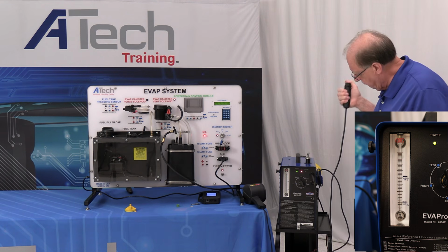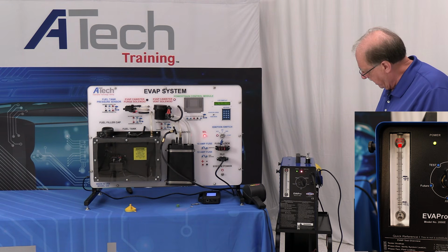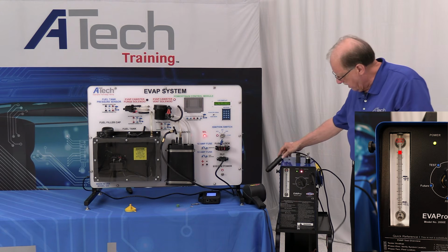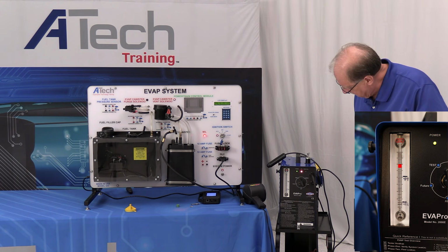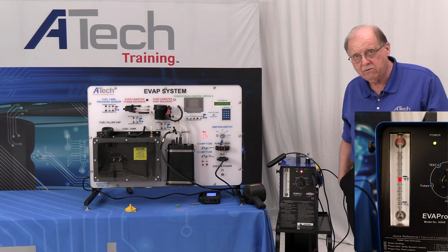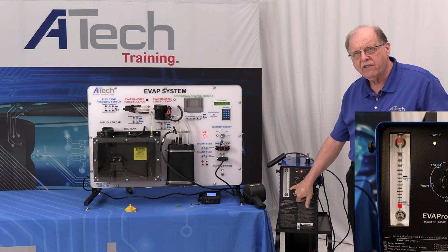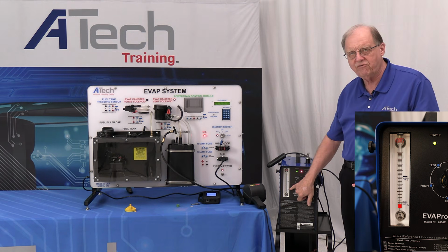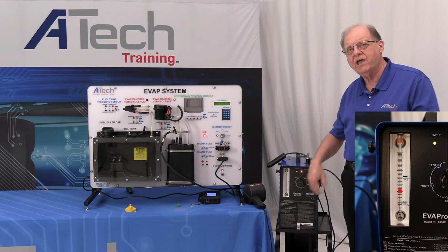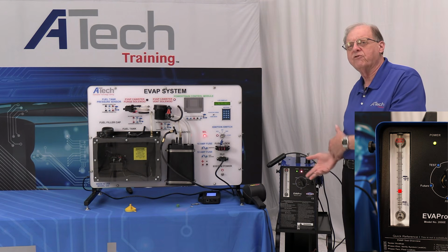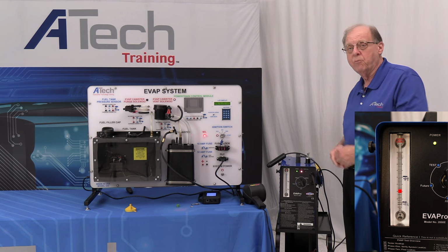So I'm just going to turn the system on, and we should watch the ball, and it should gradually go down. It takes a while. Watch it bounce a little bit. If it goes below the 20 thousandths leak here, that means we have passed. We have a sealed system. If it would be above that, we have a leak. We're going to have to do some testing. So we're going to act like we have to do some leak test, and we're going to apply smoke to the system next.